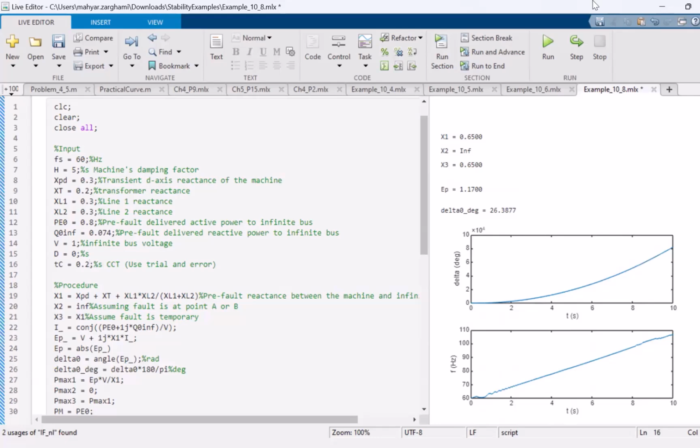So we're not really interested in the 0.000 time. That's very small. As long as we are around basically 0.01 of that type of accuracy, we should be good. But the point here is that if you're increasing the clearing time, then you will increase the chances of the system to become unstable. Therefore, your protection system will need to act fast. The faster your protection system acts, the better chance of stability you get. So this was a trial and error through simulation that I just showed you.